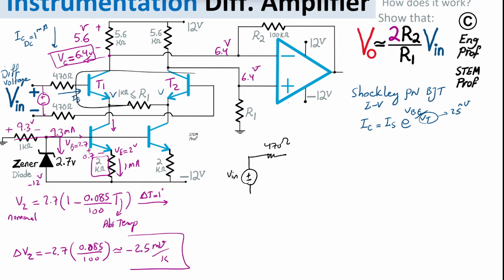These are small-signal transistors, so a small current. We're talking about the beta of the transistor being much larger than 1, for example at least 100. With that in mind, I'm dealing with 2 times 470, because we have 470 here and 470 here in the return route.